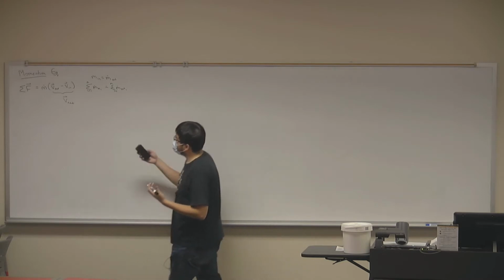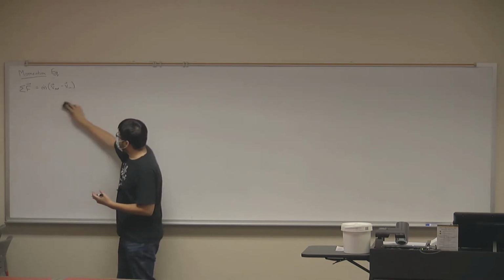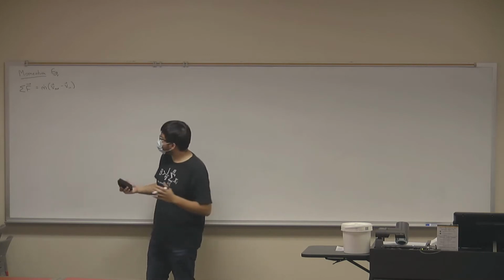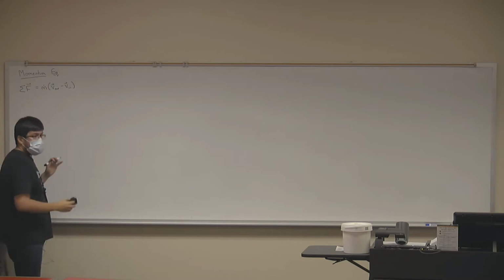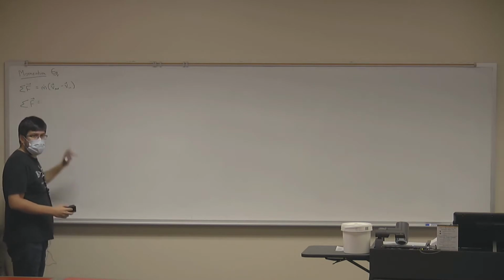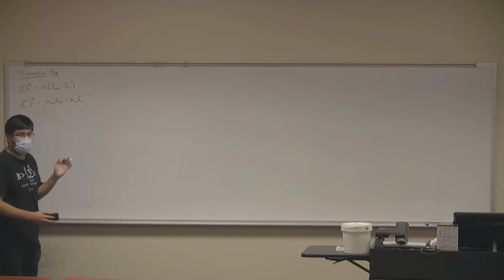We're going to look at all this in an actual example, but I do want to prepare you that sometimes the equation may not be as straightforward as what we have just derived, and it's okay when you see an equation that's not as straightforward, right? Just to avoid confusion, I would recommend that everybody rewrite this equation in the following way. Instead of setting out your mass flux as just one individual term, you may want to include your mass flux for each individual inlet and outlet.